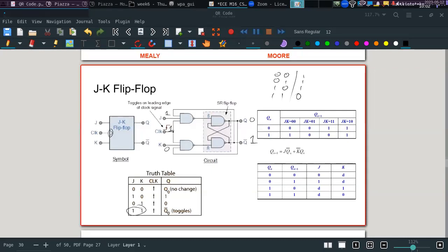We'll see that, well, right now our state is 0, so 0 goes here, and we have as an input 0 here. 1 goes here, and we have as an input here 1. So 1, 1, and 1 in an AND is a 0 here. 1, 0, 0, it's a 1. So we have here 0 NAND 1. This should give us 1. 1 NAND 1 should give us 0. And now we have changed the output. But again, this can only happen when this clock signal is 1.